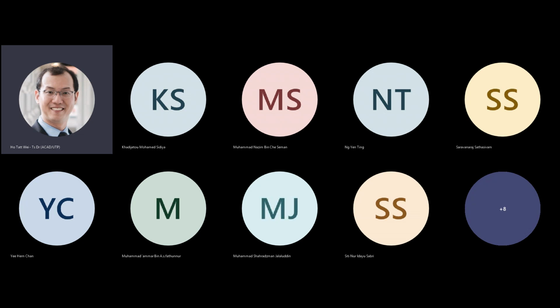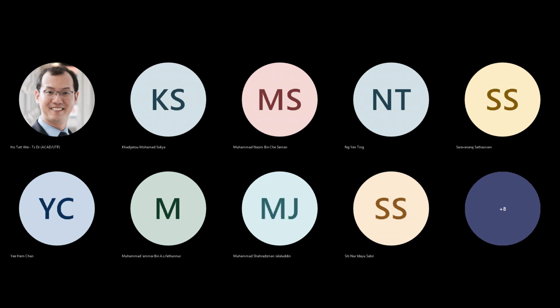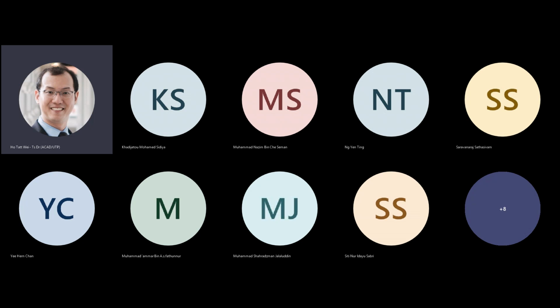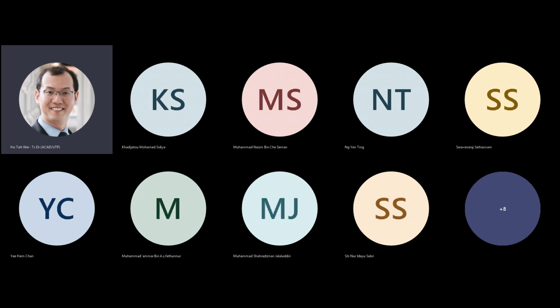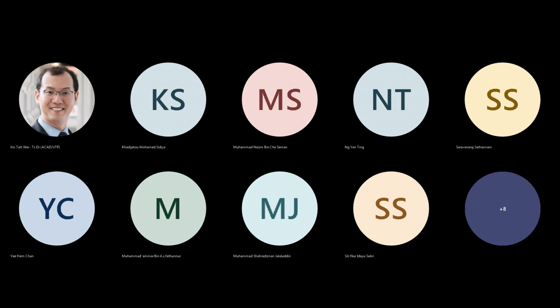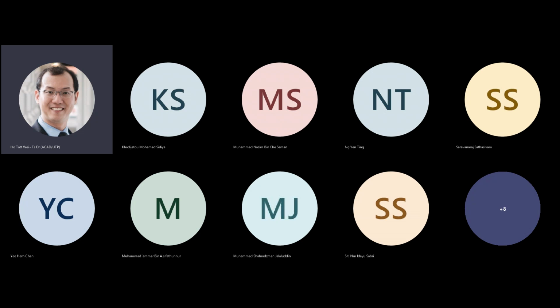So when you have two of these in parallel, and I connect their outputs together, I tie them up together, this forms a 2-input multiplexer. If I want a 4-input multiplexer, I can tie 1, 2, 3, 4 of them together, driving the same output. 8-input multiplexer, and so on and so forth.